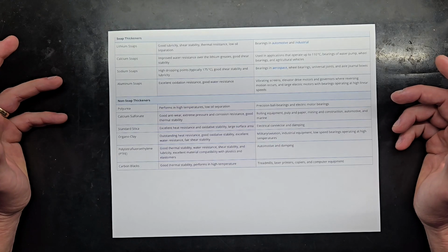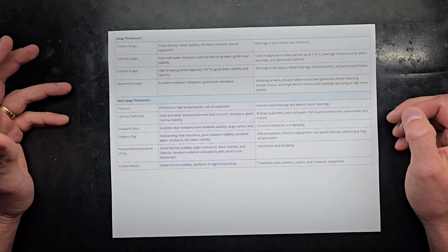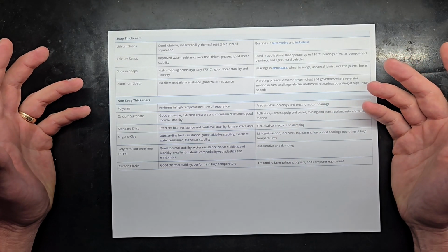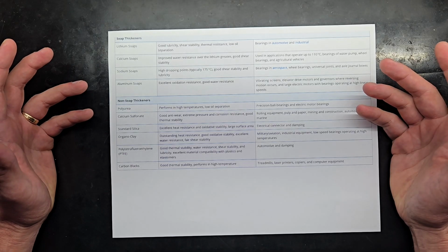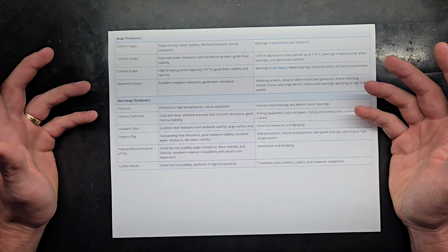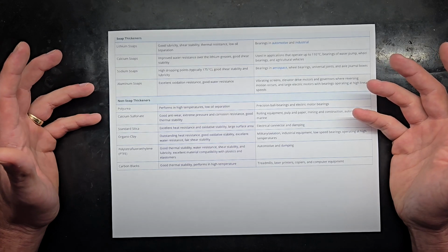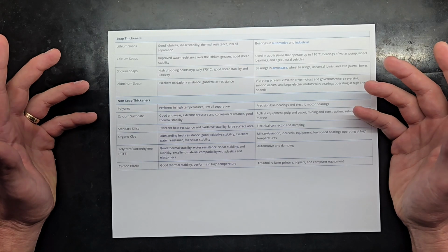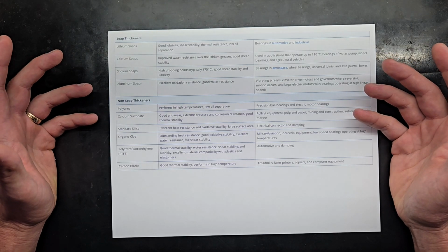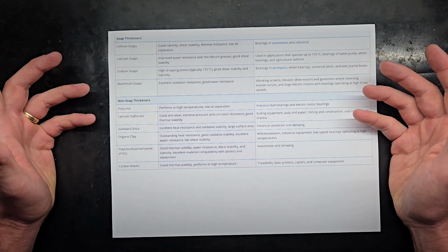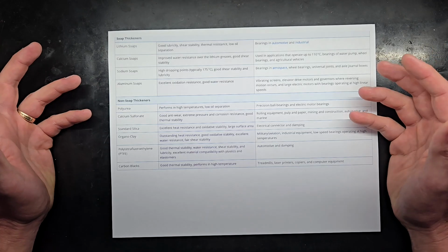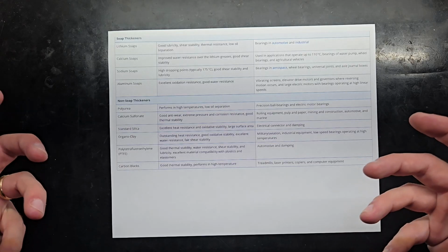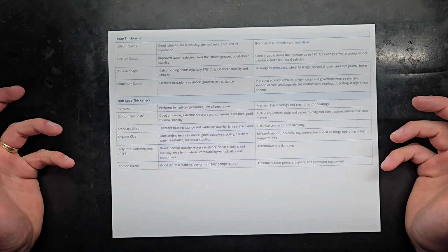But the basic way of understanding the difference between a simple grease and a complex grease, because you might see that at the store, is a complex grease has more inner linkages in the matrix. So if you think about the thickener, the soap, as a sponge, a simple soap is going to have fewer cross-linking between the spongy materials. It would be a little softer, and potentially a little more porous.